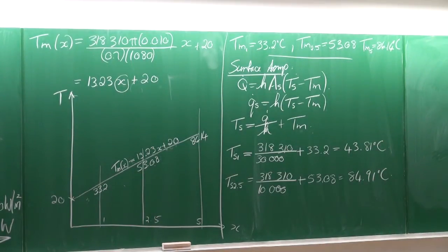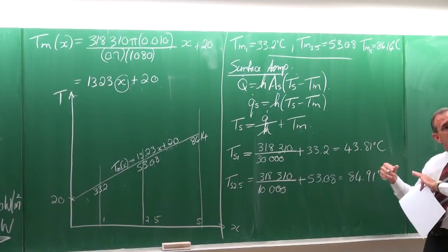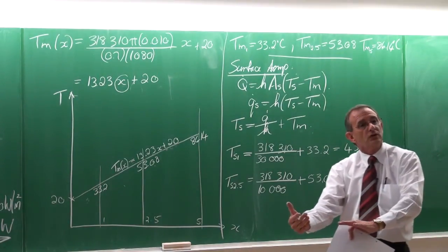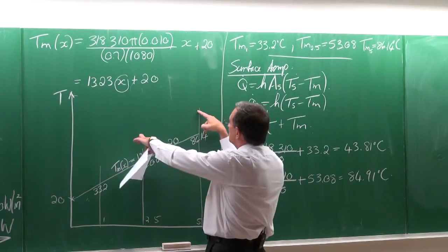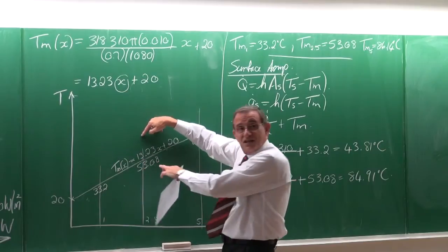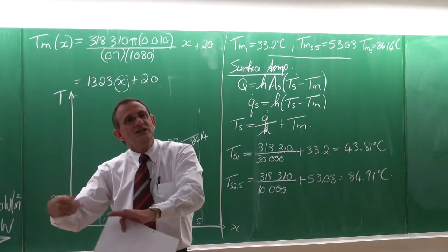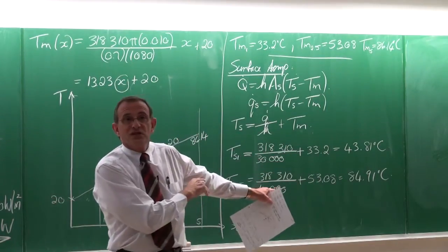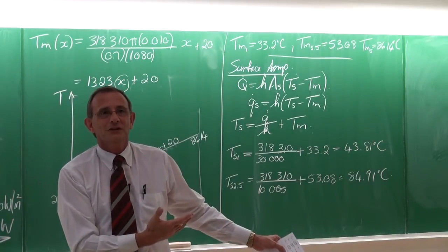How does it affect the surface temperature? Well, that is the amount of heat that you're going to transfer. So if you look at the water here, I'm going to plot the values of the surface temperature. You need that delta T to get the heat into the water. So that's the only way. So indirectly, you're calculating the surface temperature exactly like this. As long as you know it's 50 kilowatts of heat, then you've got it.